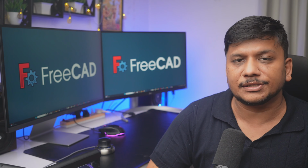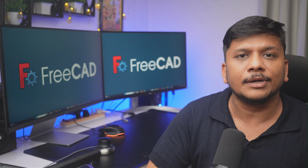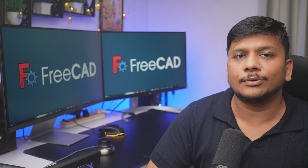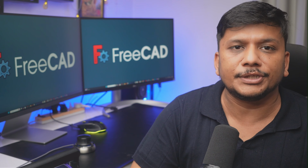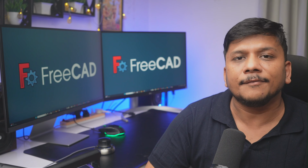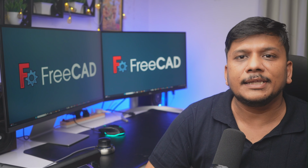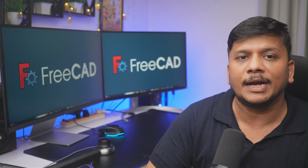If geometric constraints control relationships, which by the way we covered in our last video, dimensional constraints control the exact size. Without them, your sketch is just floating. Dimensional constraints fix length, angle, and radii with precise numbers. They are what turn a rough sketch into a fully defined design.